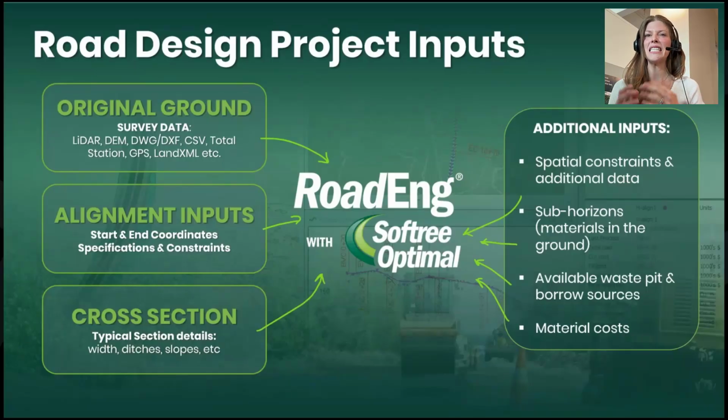And then more on the materials side of things, we can tell the software as an input what materials are in the ground, so what's available to be used, and which of those materials are to be wasted. You can then tell the software in your cross-section which materials make up which different parts of your typical cross-section, the material costs, as well as how you want to handle those materials, if you need to borrow them from somewhere, or if you need to waste them. There's a lot of other inputs that we can bring into RoadEng to help out realism. So again, focusing today in this introductory webinar on the left-hand side of the screen.